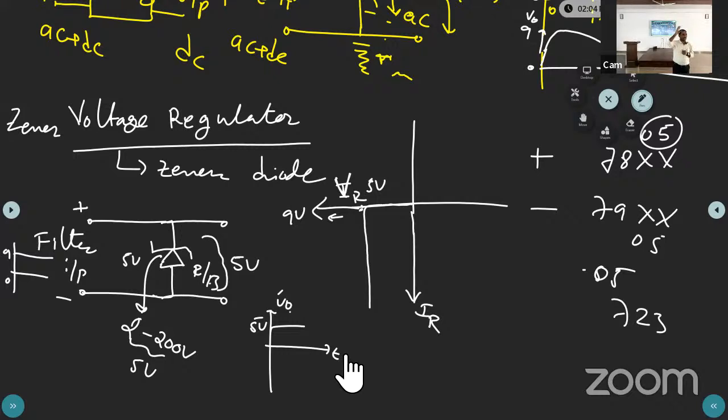We drew the input characteristics and the output characteristics, and based on the output characteristics, the transistor can be used for different applications. One is switch and the other is amplifier. If the transistor works in the active region, it acts as an amplifier. If the transistor is in the cutoff region, meaning both junctions are off, in reverse bias, that is the off switch.